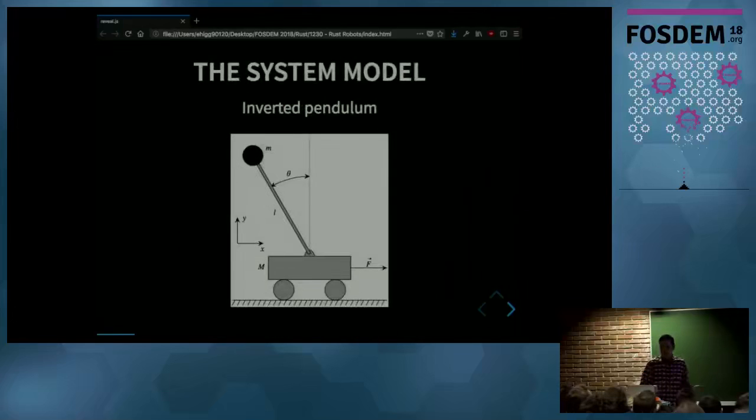This is similar to a common problem in control theory, the inverted pendulum problem. In that problem, we have an inverted pendulum on top of a moving car, which you can move using this force F. The pendulum will fall due to gravity, and to compensate for that falling action, if the pendulum is moving to the left, then you also have to move the car to the left. So the problem boils down to picking a force F according to the tilt angle theta that you see there.